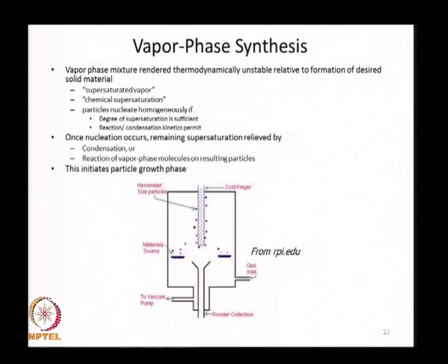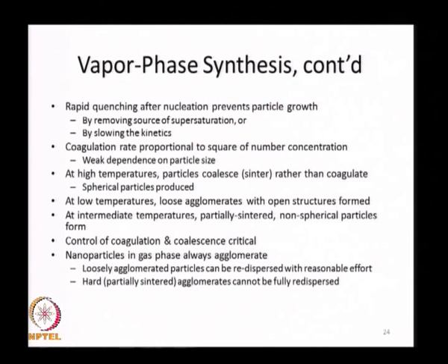If you recall that trimodal particle size distribution that we had sketched in one of the earlier lectures, the nucleation process has to be followed by a growth process in order for the cluster sizes to keep increasing. Now, sometimes you do not want the growth, you want the nuclei to remain as nuclei, you want the dimensions to remain essentially a few nanometers in size rather than growing to tens of hundreds of nanometers. Then what you need to do is quench the growth.